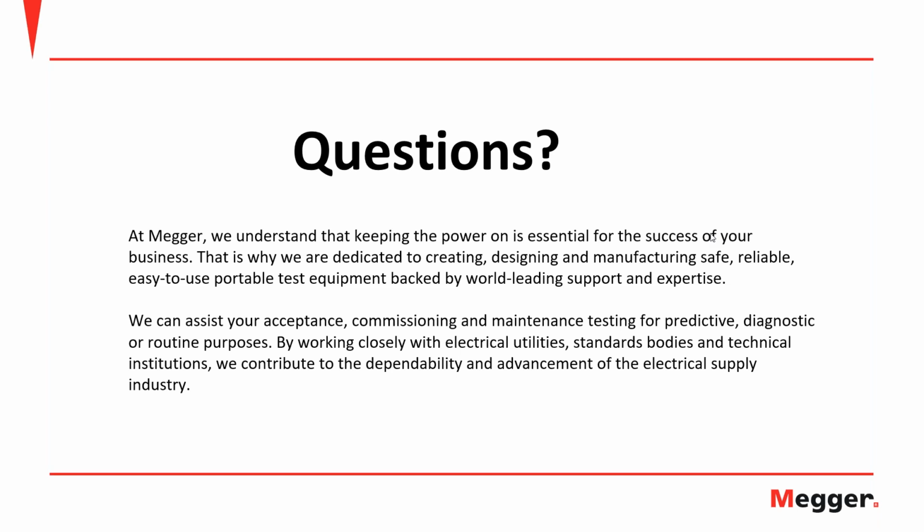Usually what I've seen is that it doesn't break down at 2 millimeters. So pretty much the standard is that you go directly to the 1 millimeter value, because that's where the oil will break down. If you have an instrument that can go higher than 60 kilovolts, for example 80 kilovolts or 100 kilovolts, you may get the oil to break down at 2 millimeters, but typical field testing is 1 millimeter.